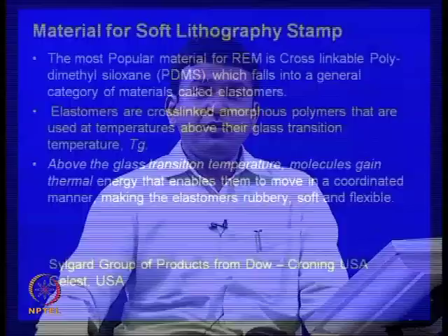So, this is important. If a material is exhibiting room temperature elasticity or is flexible at room temperature, the first thing you need to know is that, unlike a homopolymer film we have been talking about so far, where you just have entangled molecules but no physical binding between the individual molecules, an elastomer will invariably have molecules that are cross-linked.